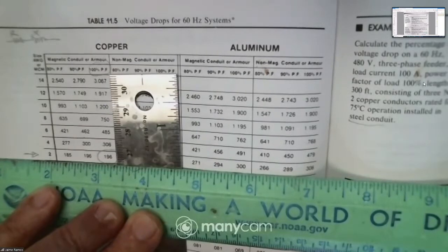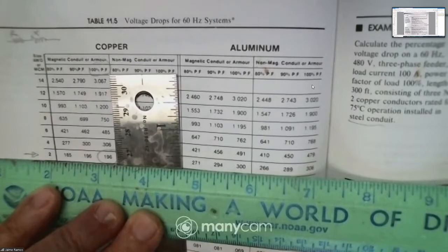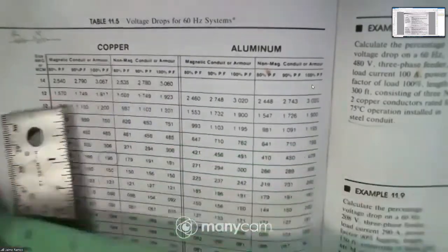Now it's going to be compared with the voltage drop. So 10.2 is the voltage source minus voltage load. Divide 10.2 by the 480, which is the source. Then the percent is 2.1%. So that's a good case.